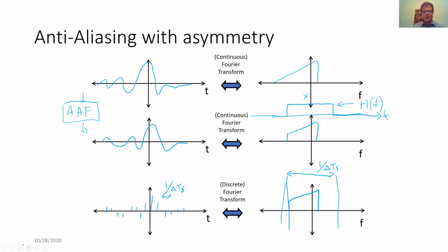All right, but this is another example of going through these aliasing pictures, remembering that when we do our data sampling, we're going to have a sampling rate or a sampling time requirement called the Nyquist criteria that's going to ensure that we don't get aliasing, or when we can, we may be applying an anti-aliasing filter to prevent that from happening.